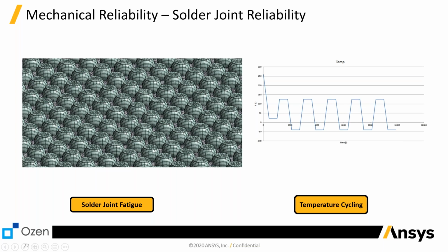It's also important that when you start meshing every single one of these, you may want to copy the mesh on one and duplicate the mesh on the others. ANSYS has that capability, because you don't want to mesh different solder joints with different meshes.